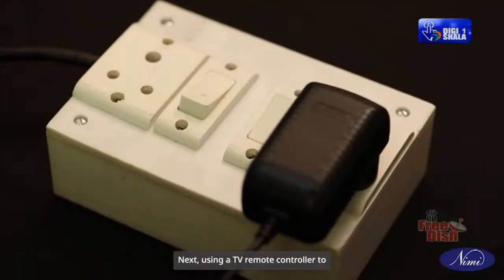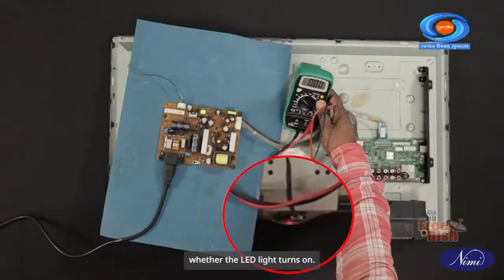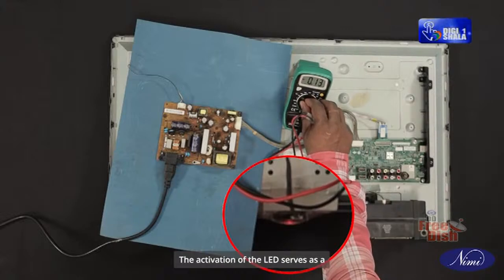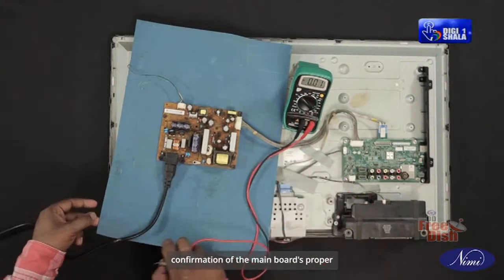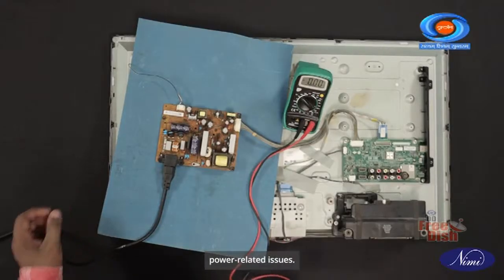Next, using a TV remote controller to power on the television, closely observe whether the LED light turns on. The activation of the LED serves as a confirmation of the main board's proper functionality, ruling out any potential power-related issues.